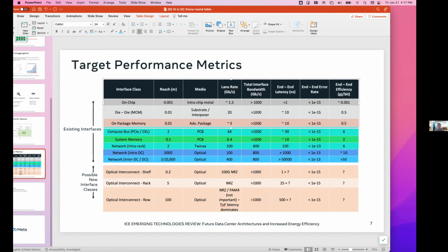Yeah, so I think, Rob, some of the challenges with HBM is also we are seeing the temperature gradient from top of the stack to the bottom of the stack, because now HBMs are coming into 8 and 16 high. That is also creating a lot of gradient and making an efficient cooling system around that harder. So the thought process is, can we do system level disaggregation where we can have a common place where we have all the memory and then our accelerator can access all that memory.